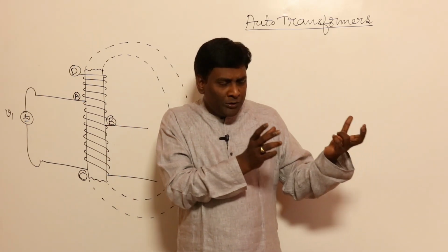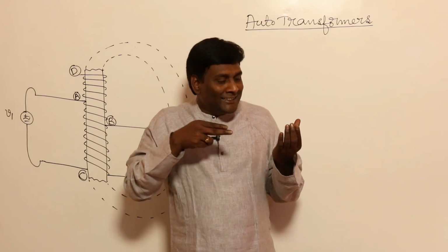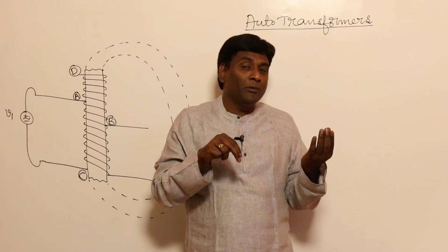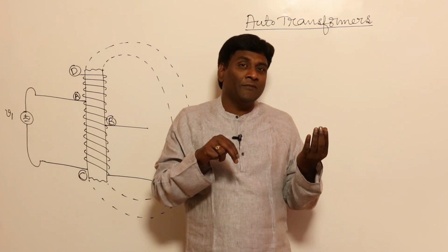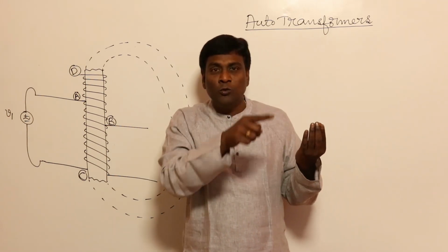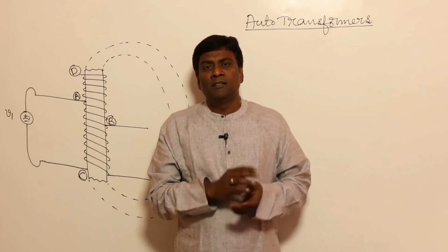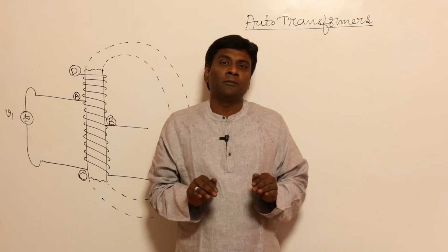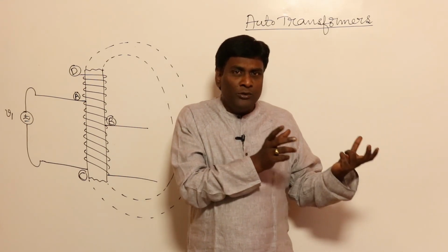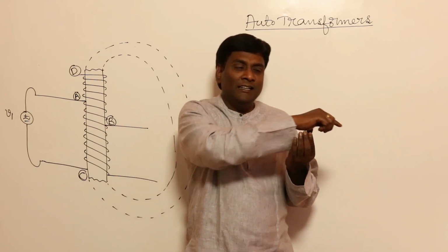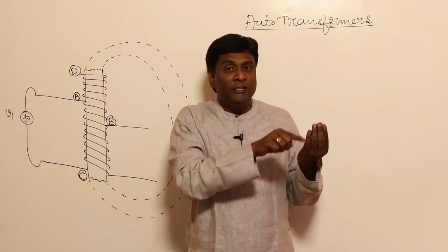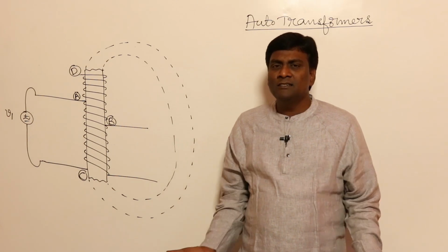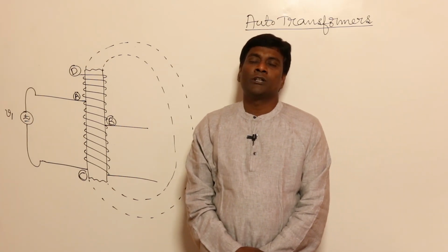Now if you take the same machines lab rheostat and insert the iron around it, relative permeability is more, so inductance effects will be more, and we have that nichrome wire. So let us reduce the wire resistivity to copper. Machines lab rheostat, insert iron inside, close the iron, and reduce the resistivity of the wire to the least possible by using copper wire. That is nothing but auto transformer.